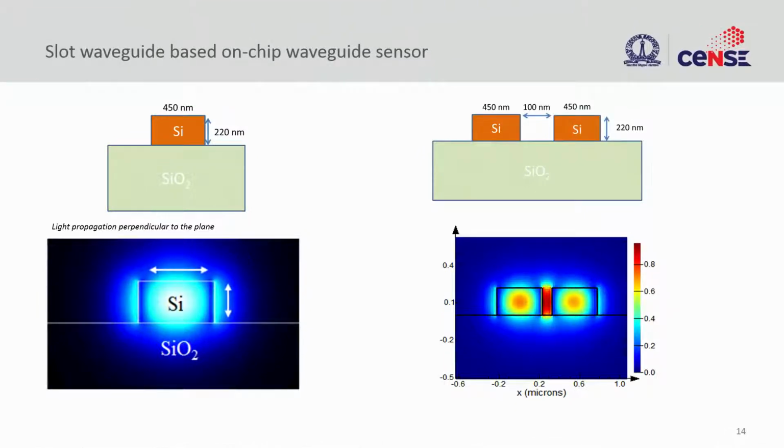Right. And the light matter interaction, as I mentioned, is important here. So, this is a typical waveguide structure, and what you see is the electric field. So, this is nothing but the E field of a TE mode, right, transverse electric mode. So, it looks something like this. You have electric field outside, only this much available, but you can see here most of the light is sitting at the center, right, inside silicon in this case. So, only a very small fraction is available for interaction outside.